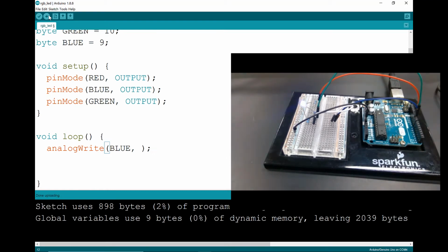Okay, so analog writes and pulse width modulated signals allow us to simulate analog outputs. In this case, that means we can drive the LED to produce light in a graded fashion. Instead of all or nothing, we can produce light of varying levels, at least we perceive the light to be emitted in varying degrees of intensity. So you can do more fancy stuff.